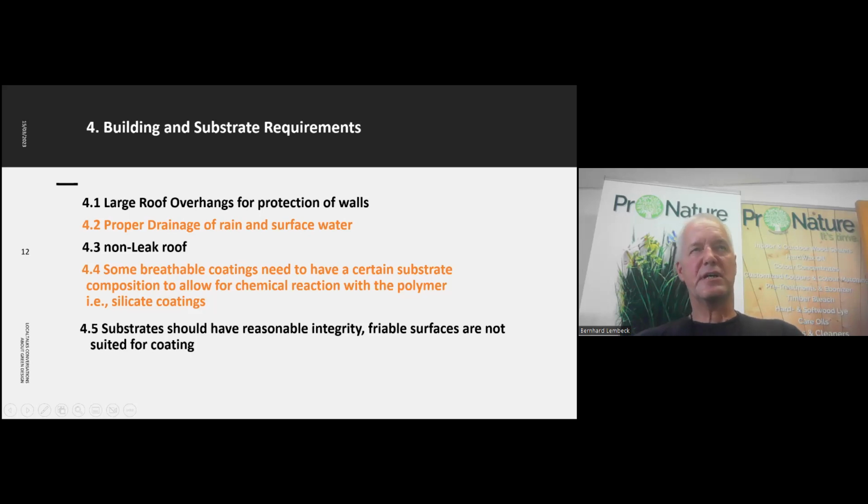but just looking at coatings is probably not quite cutting the thing. What we prefer to see, especially on buildings that have utilized natural building materials, we like to see large roof overhangs, which is in South Africa hardly ever the case, and we even in conventionally built buildings see the detrimental effects of the weather, whether it's now from sun bleaching or wind and rain. They're rather detrimental, especially in these very fast developed settlements.